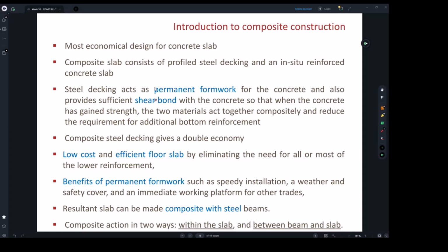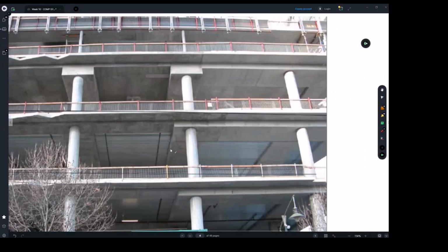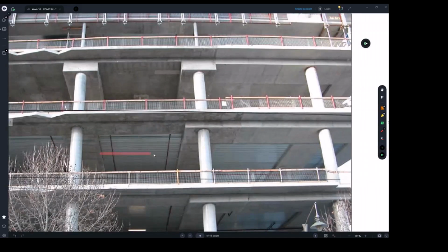However, still you need to prop the bonding. Let me take you back to this image. If the span from here to there you're trying to pour was only about 2 to 3 meters, then maybe you've got a situation where you don't need to put a propping line. You don't need to prop it in the middle here.